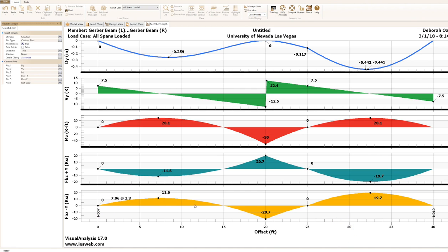One side is an overhang, something we learned in Structures 1, and a simple span with 2 point supports, 2 pin supports at the right hand side, behaving exactly like a cantilever span, not exactly like a continuous span, and saving some material. So if you have a bunch of beams, you get a reduction in weight, reduction in cost. You also make a shorter depth, and so you can put in pipes and ducts and things like that. This is also much less sensitive to movements and settlements and so on. And that's how we can manipulate beams in visual analysis.